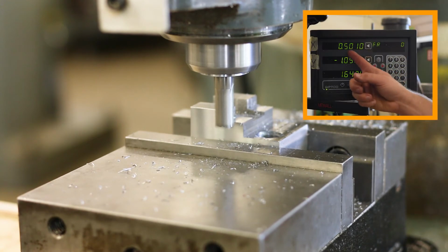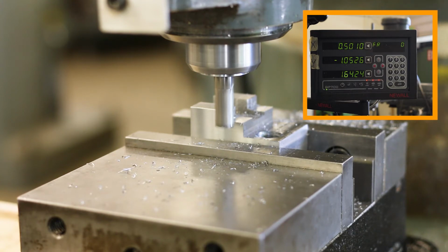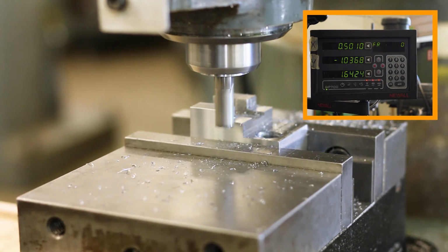So looking at my digital readout, where I just touched off is 500 thousandths of an inch from where my last cut was, from where the last step was, okay? And actually, that's where we're supposed to be. There's supposed to be a difference of 500 thousandths there between the positions of the two steps. I'm going to go ahead and lock this down and take a cut.